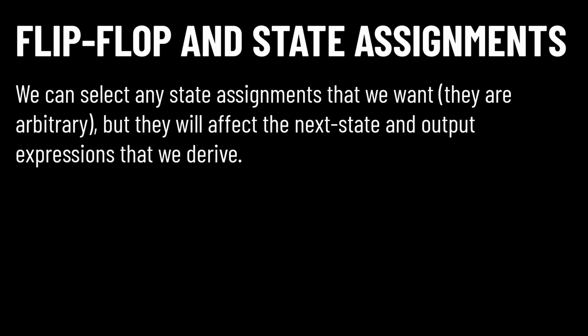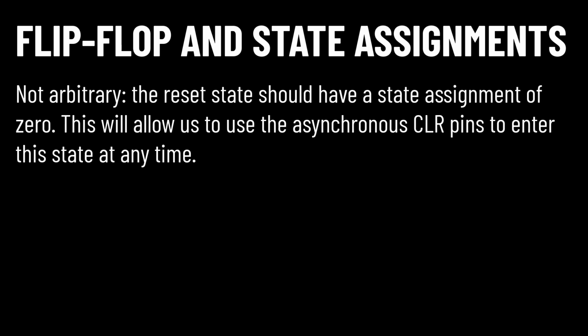While they are technically arbitrary, we'll see that state assignments do affect how our circuit will be built. A poor selection of state assignments can lead to expressions that have more gates and inputs than a better selection of state assignments would have. The state assignment that is not arbitrary is our reset state.